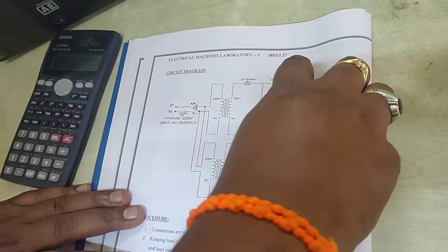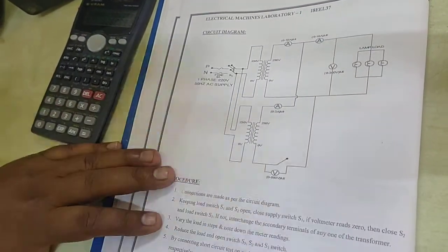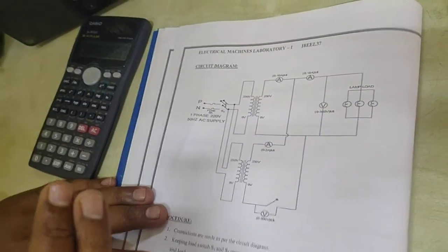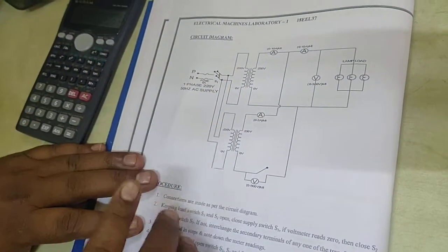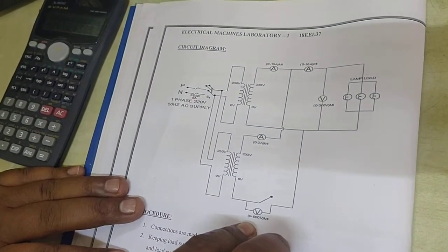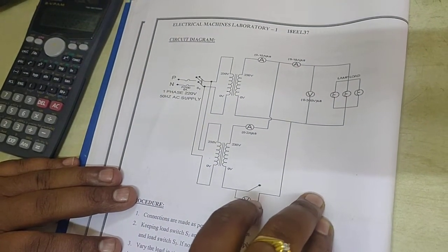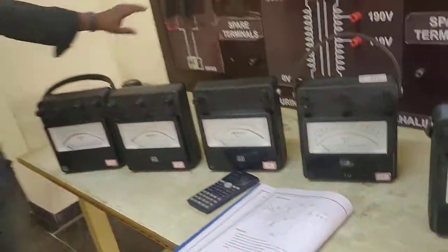The voltage across the load will be 0 to 300 volts, and one more voltmeter across the switch to check the polarity of the transformer. Always the polarity should be subtractive polarity. If it is additive polarity, then we have to reverse the polarity of either one of the transformer secondary sides. It should always be subtractive polarity, meaning if we add both voltages, the total voltage should be 0. Only then can you conduct the experiment. So we are going to start the experiment.